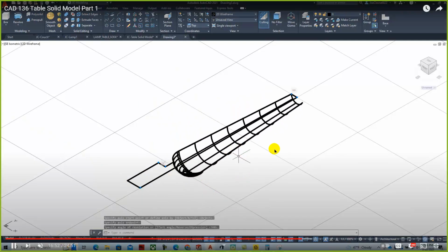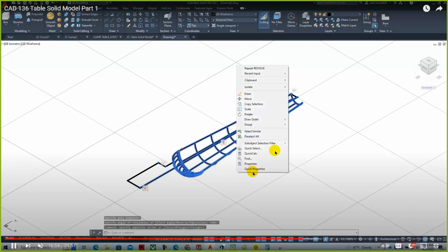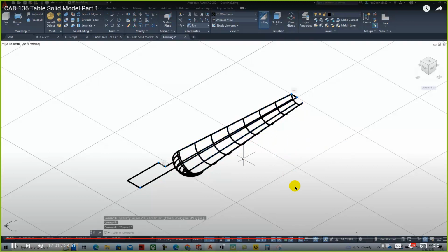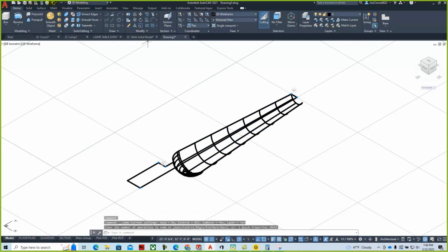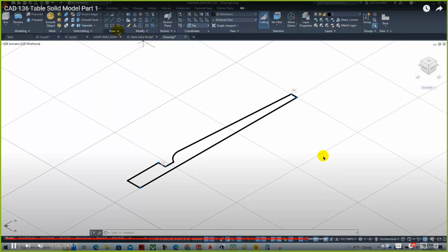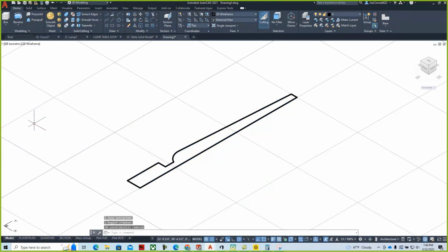And so this is showing what happens if we don't have one as a surface, which visually looks okay, but from a standpoint of prototyping or making things with modern manufacturing like computer-controlled routers, we would want solid models. And so we go through and create the 2D geometry, make a region out of the part, and then when we revolve it, we'll be able to revolve that as a solid.